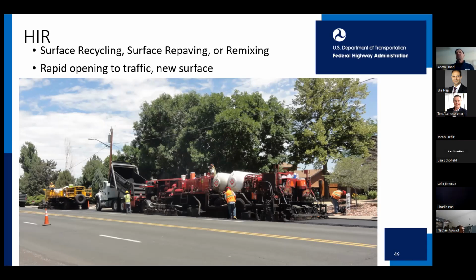Some of the benefits with hot in place recycling, so really positive benefits, are, one, you have a renewed surface regardless of which technique you use. You end up with a renewed surface, and another is it's like hot mix, right? You can open up the traffic the same day.